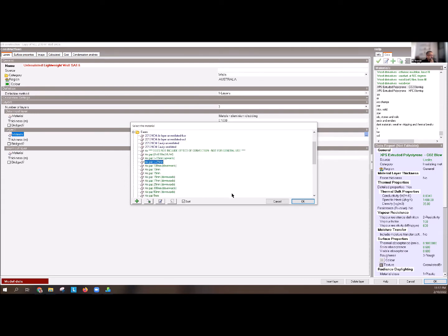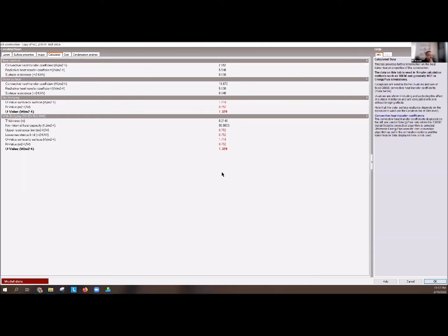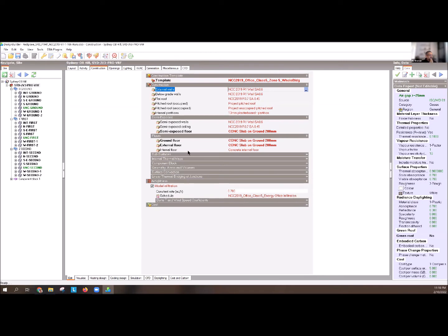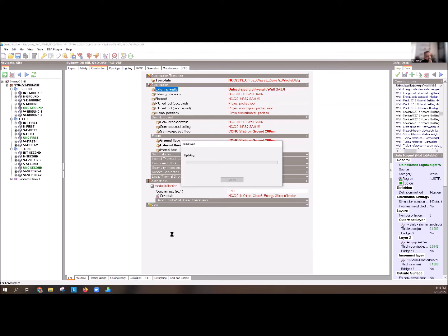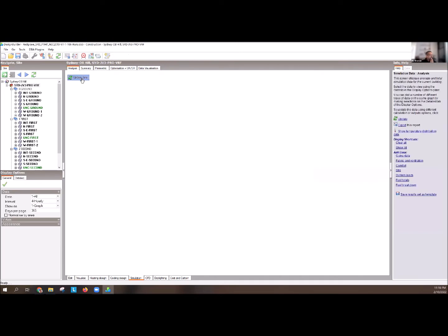If I put in a 25 millimeter air gap, it gives an R value, which you will find here, of 0.18 for the air gap. You can calculate the total U value over here, 1.3 something. But if we rerun this simulation, then you can see what the change is in terms of just changing the insulation on the wall.